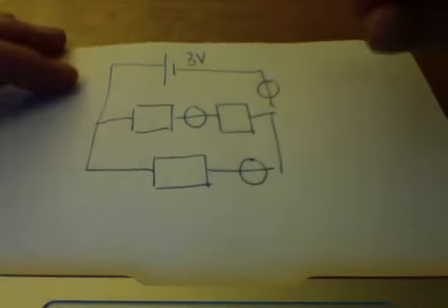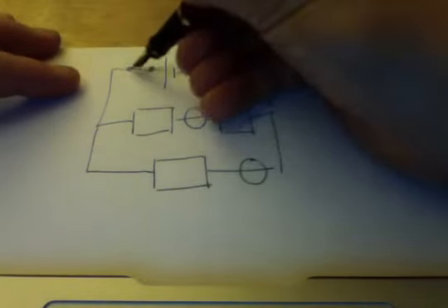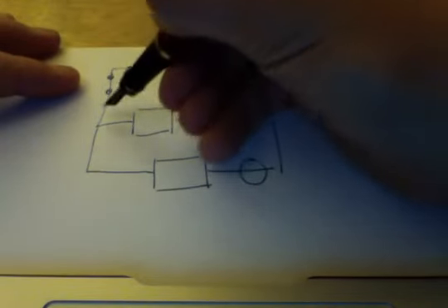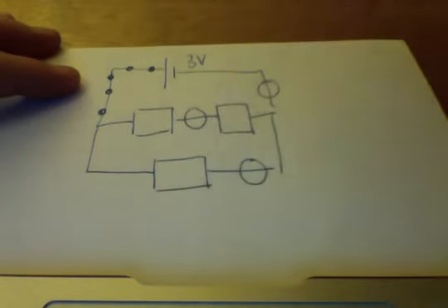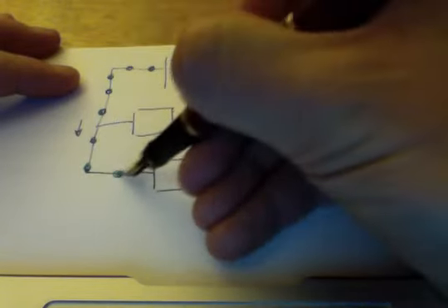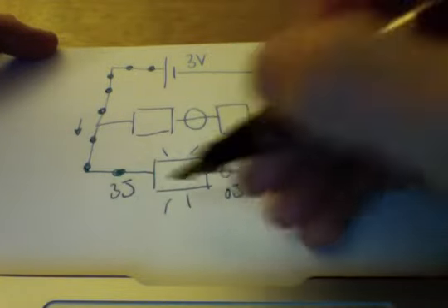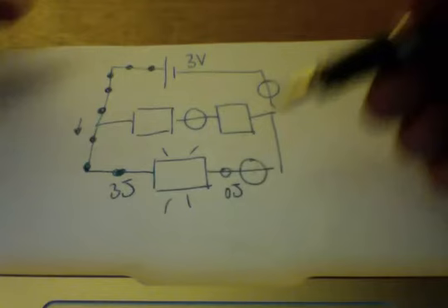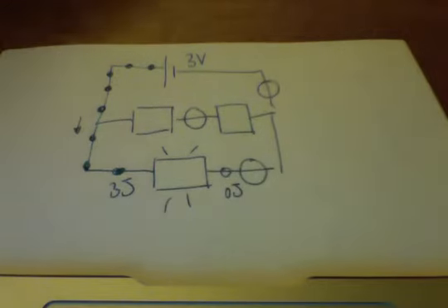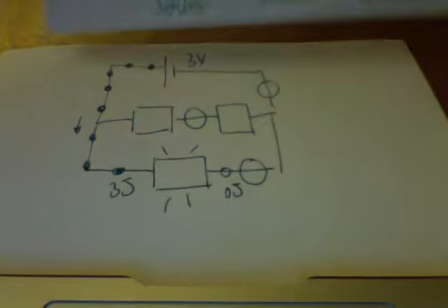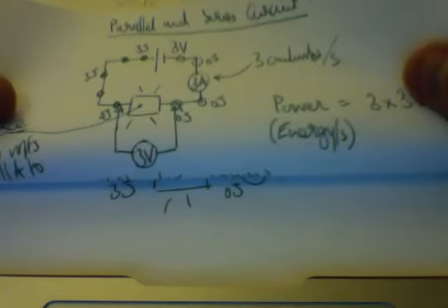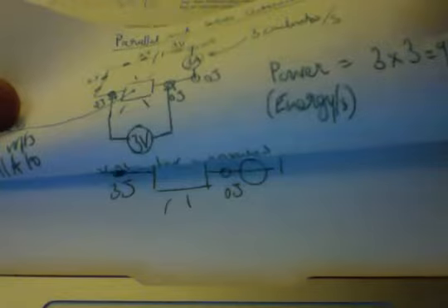Okay, what's taking place here? Well, simply, the coulomb comes out of its battery, or cell, and at this point it makes a choice. Let's deal with this choice first. Let's imagine it's going along the longer arm, and what I'd call the simpler branch, because it has 3 joules and it uses all of those joules in that resistor. So in essence, we're back to exactly what we had in the first circuit, which gives us 3 amps.